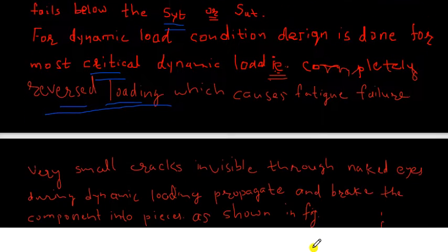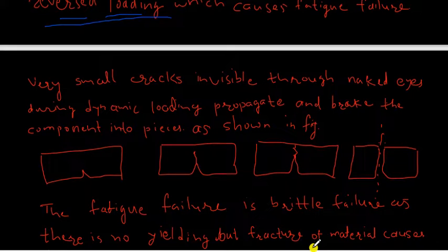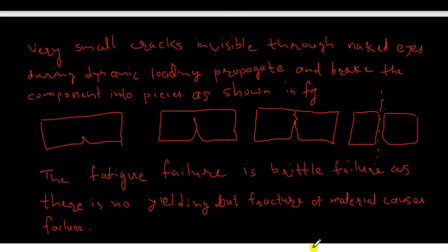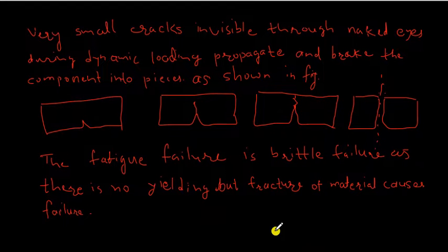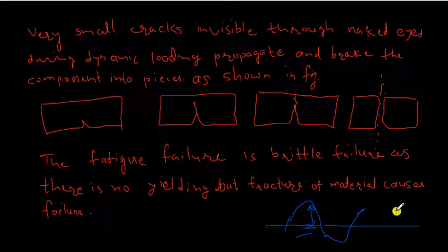Because if you put in the values for each case and find where the stress amplitude is maximum, you know that the stress amplitude is shown like this, from here to here, in this figure. If this stress amplitude is maximum, then that loading condition will be the worst and the component will fail in that case at the earliest.